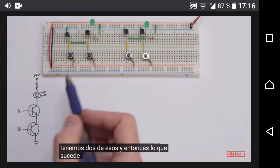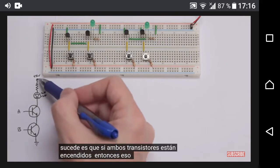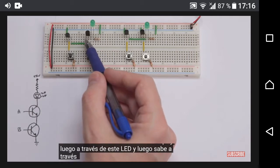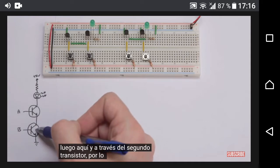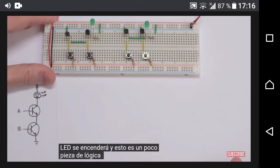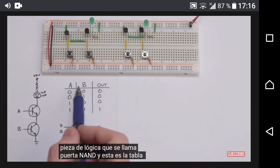And so what happens is that if both transistors are turned on, then that will complete the circuit through this resistor here, and then through this LED, and then through the first transistor, and then over here and through the second transistor. And so if both transistors are turned on, then the LED will turn on. And this is a little piece of logic that is called an AND gate. And this is the truth table for it.